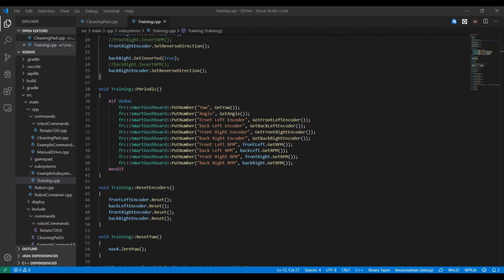Now, if we want to drive the robot around manually, in the control station console, we want to make sure we are in teleoperated mode. If we're not in that mode, you can hit O and it moves to that mode. Now my controller is plugged into my computer by the X marked here.